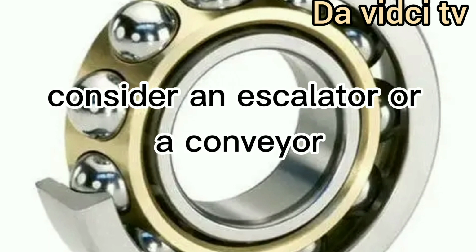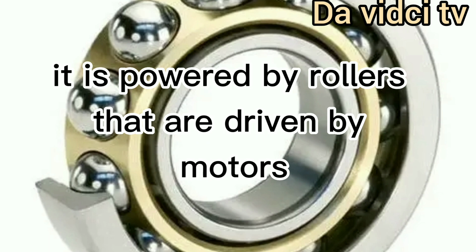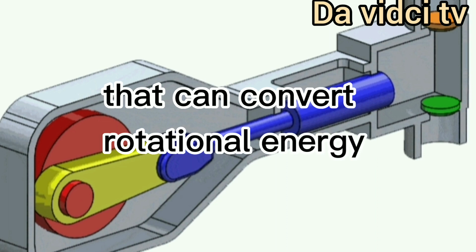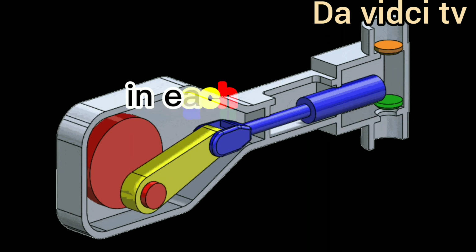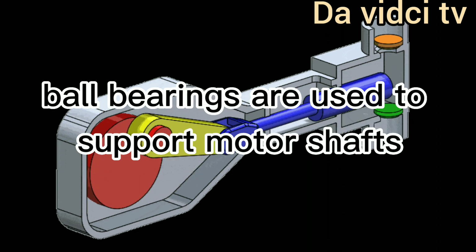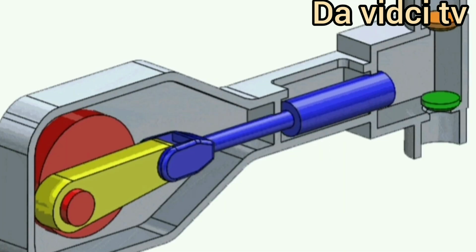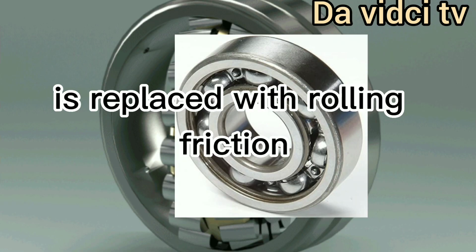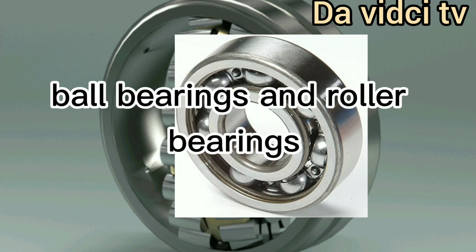Consider an escalator or a conveyor. Even though the motion is linear, it is powered by rollers that are driven by motors. Another example is a reciprocating pump that can convert rotational energy from a motor into translational motion with the help of linkages. In each of these applications, ball bearings are used to support motor shafts as well as shafts of other rollers in the assembly. Rolling elements carry the load without much friction, as the sliding friction is replaced with rolling friction. Rolling element bearings can be subdivided into two major types: ball bearings and roller bearings.